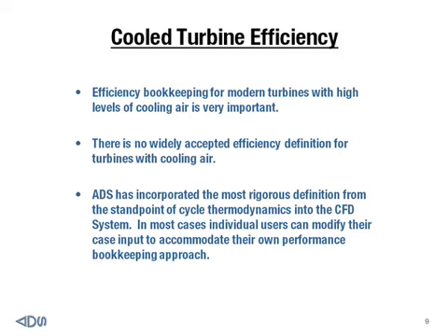Now, moving on, as I mentioned, the efficiencies that were given previously do not recognize cooling flows. Today's modern turbines run at such high temperatures that cooling is necessary and needs to be properly bookkept in the design of these components. There, surprisingly, is no widely accepted efficiency definition for turbines, and different manufacturers have different definitions.